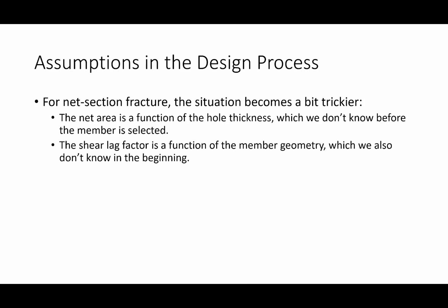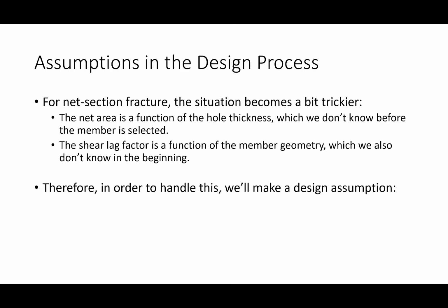That's the problem with net area. What about shear lag? Well, we have no idea what the shear lag factor looks like, because the shear lag factor is a function of the member geometry, of the connection geometry. We don't know what that is in the beginning either. Excuse me. So, what do we do? In order to handle this, we have to make an assumption. We have to guess something. Okay? And what I'm going to guess is this.